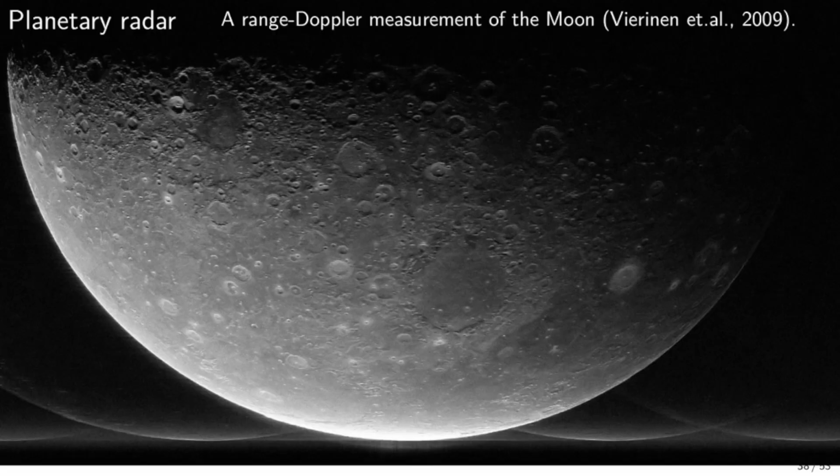Planetary objects often have a very narrow Doppler extent. This allows us to use coherent radar target techniques when estimating the radar scatter from planetary surfaces. Planetary targets are also very far away. Often very long transmit pulses are needed in order to reduce the estimation variance of the scattered complex voltage.